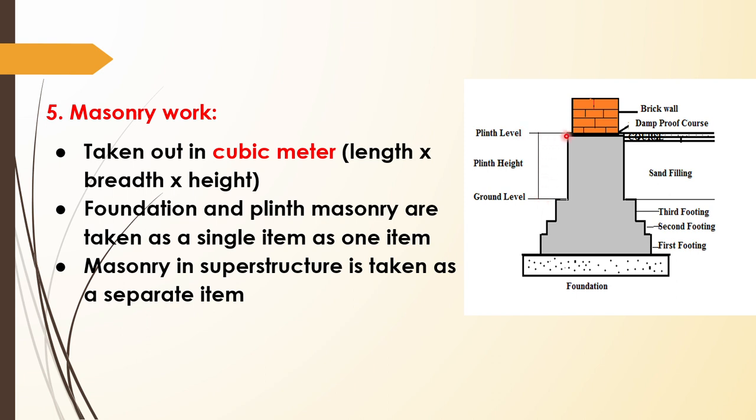Above that there will be an exposed foundation, that is plinth level. So this is the plinth level. This height is known as plinth height. Above that our superstructure, that is our walls of the buildings, will come. So here we will provide the damp proof course.